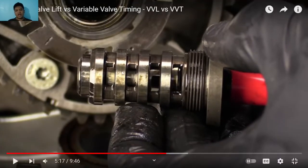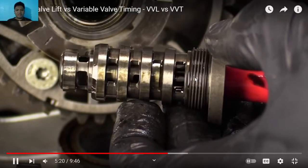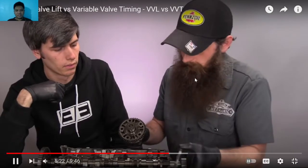This is the valve that I was talking about. This is the one that controls the oil to go in one direction or the other, depending on what the ECU tells the camshaft. To pass oil through this. There's actually another part to it right here that you guys don't need to know about, so I don't know why I picked it up.